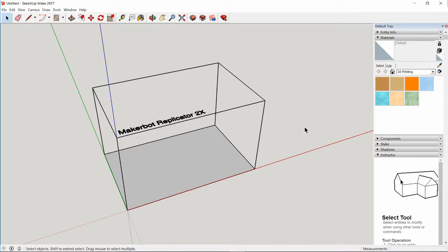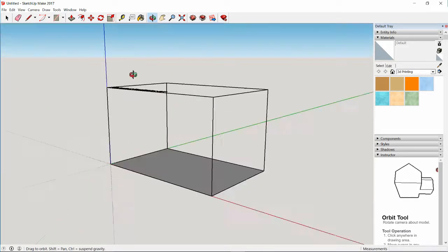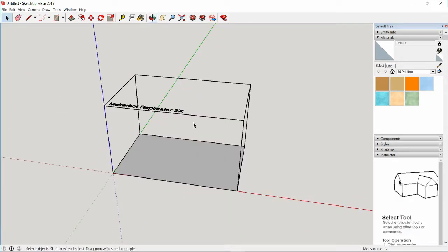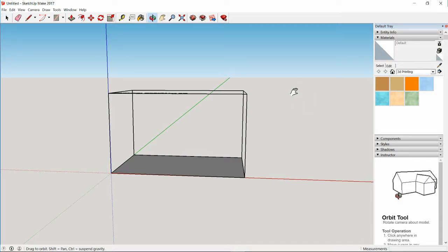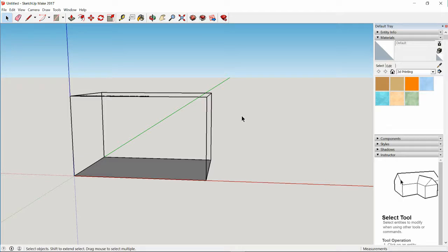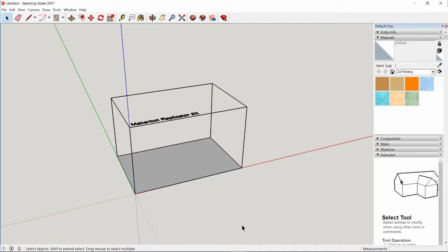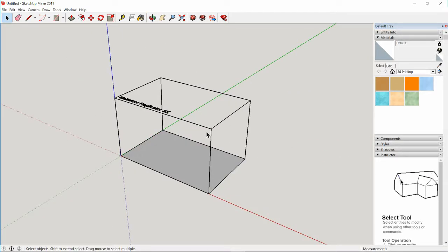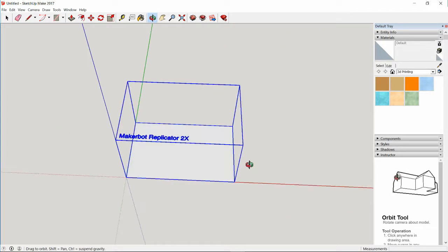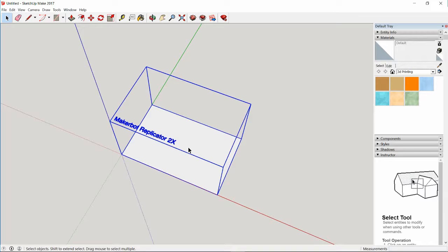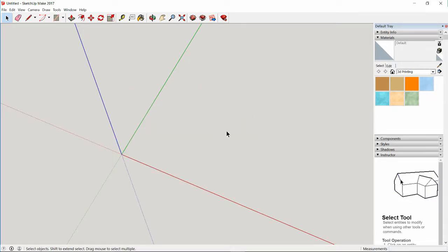So the controls for SketchUp basically are if you hold the mouse wheel and move your mouse, then it'll rotate the perspective. If you hold Shift and press down the mouse wheel and then slide the mouse around, it'll pan. And then if you left click, that can be used to select stuff, and you can see if it's selected, it'll be highlighted blue. And you can just click off again with the left mouse to unselect. Right mouse button doesn't really do much in this. So as you can see, this is like a 3D setup. You have your X, Y, Z scales. For now, you can just click on this little default object, I guess, and you can click delete.